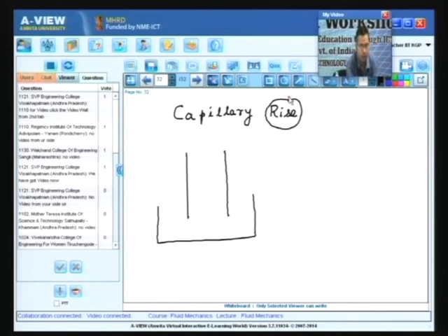We will describe what a contact angle is. Now, let us say you have an interface here, and when this capillary is dipped in this bath, the fluid gets displaced and moves up by an average height of h.